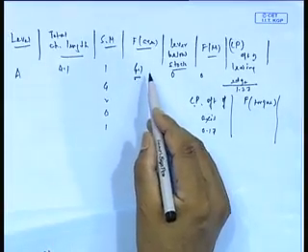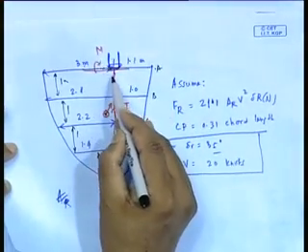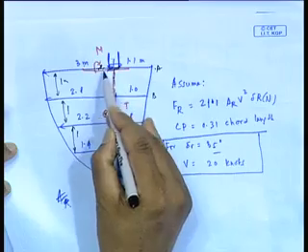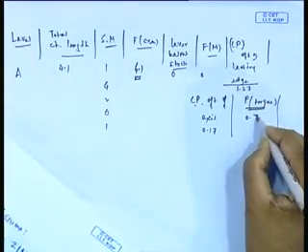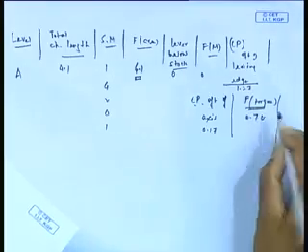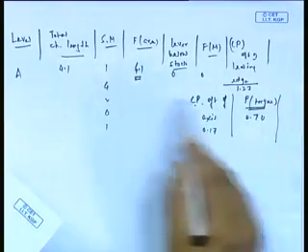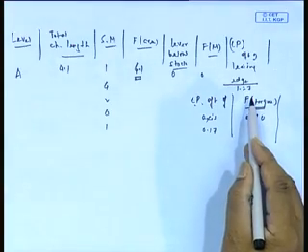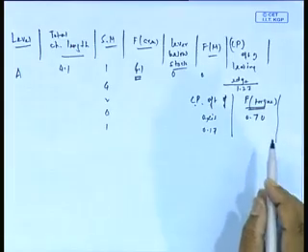Where is that? Okay, this actually is function of torque, because what we are trying to find out is this area that comes here, because it is proportional to that into this distance. We are going to be writing there as 4.1 into 0.7, 4.1 into 1. This function of torque, right? Okay, with the Simpson's multiplier.